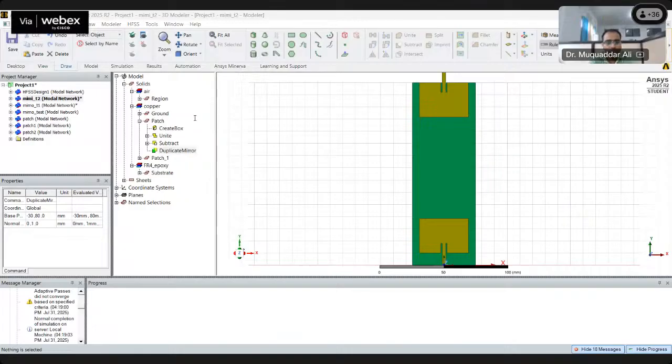And we are placing this mirror at 0 in the x-axis, the center of the mirror, and in the y direction LG plus LX divided by 2. So whenever you are using variables, you have to calculate these dimensions. So instead of LX, I should be using LEX. And now click OK.